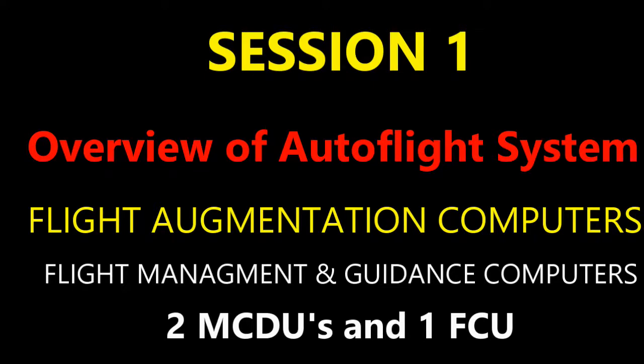Let's say you have a master caution or the master warning lights on. Those are activated when you have a disconnect of the auto flight system. You have the auto land as well. You have an auto land warning that's activated when there's something wrong during final approach. Remember, I said this is a fail operative AFS, a fail operative auto flight system. So when something happens, the next step is the operation of the ILS approach and auto land. So just remember where the attention getters are located. They're located on the glare shield panel, for each captain and first officer.